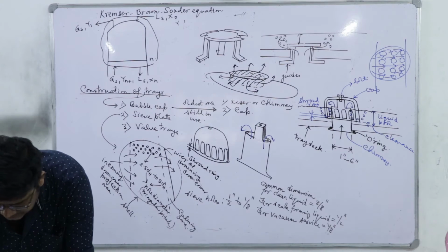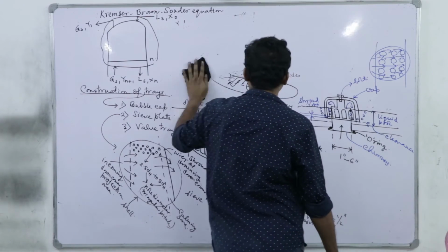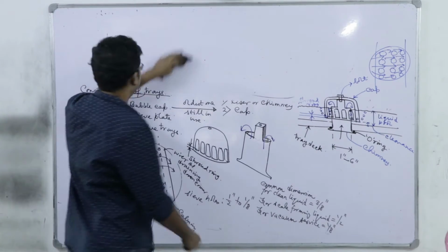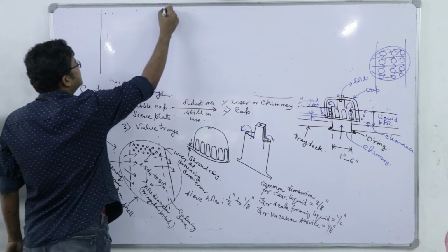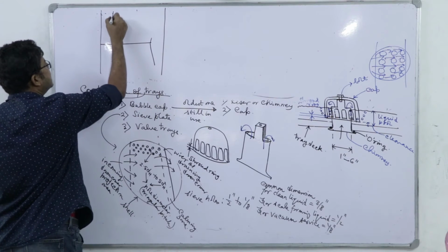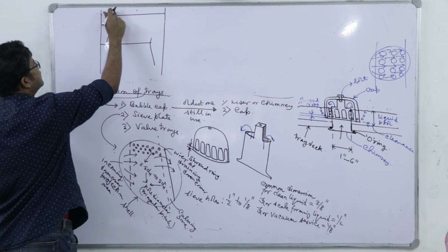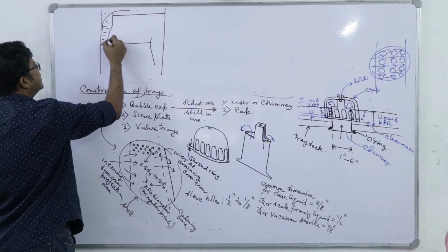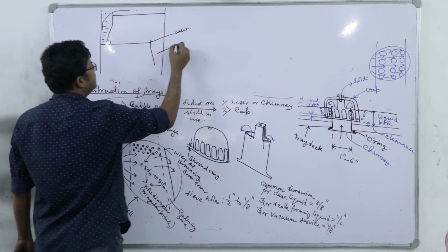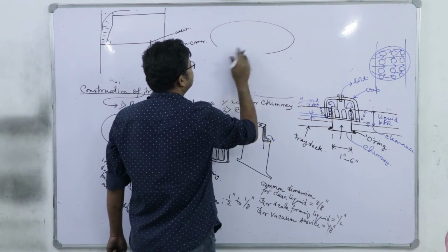Once we have discussed the three different types of trays, let us discuss the downcomers and weirs. The downcomer, the basic construction, we already have an idea. If this is the sectional view of the column, this is a single tray, this is the downcomer, and here it is the delivering downcomer into that column, here we have another tray. So, here we have an inlet weir, right. The liquid from this tray moves to the downcomer, and here we have the weir. This extension is called weir height, right. This is the downcomer, right. So, actually in 3D it looks like this.